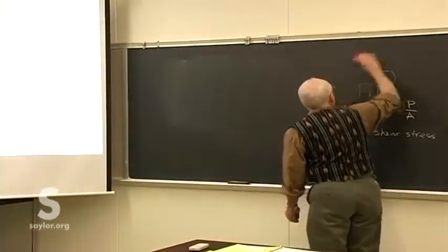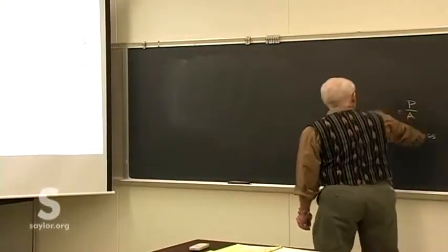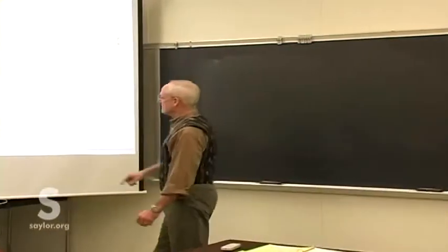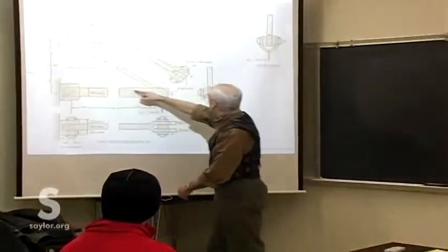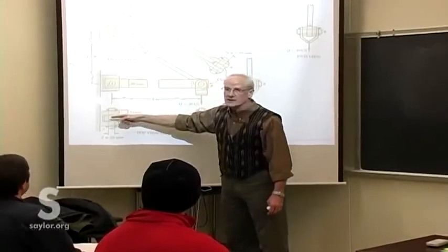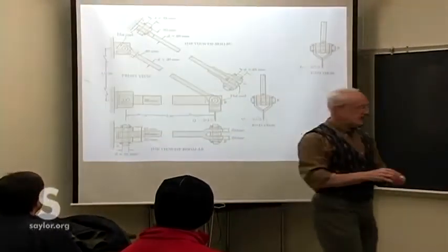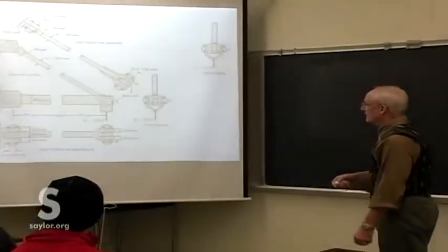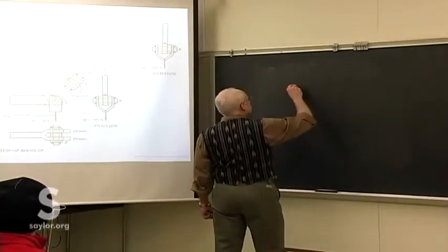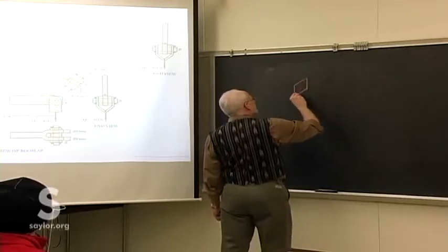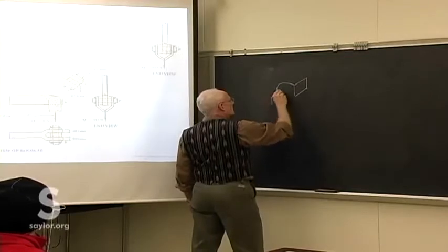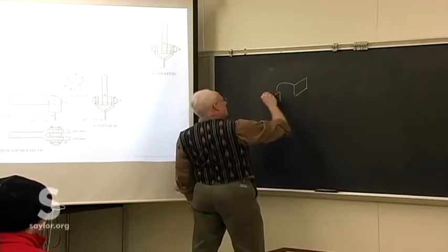Let's refocus our attention on this pin A here. Remember, this member AB is in compression, so that member is pushing on the pin A, then the pin A itself is pushing on the bracket at A. So if we take sort of a cross-sectional view of that bracket,